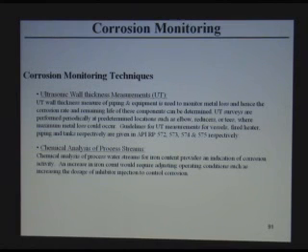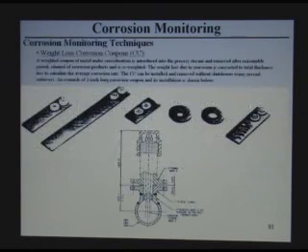It also tells you how much H2S you have in the water. Is it highly corrosive or not? How much chlorides are in it? If you have cracking in stainless steel, or you have chlorides in this system and low pH, then you have an environment that causes cracking. So this chemical analysis of water process streams is very useful.